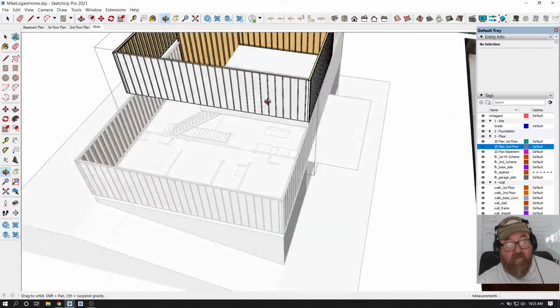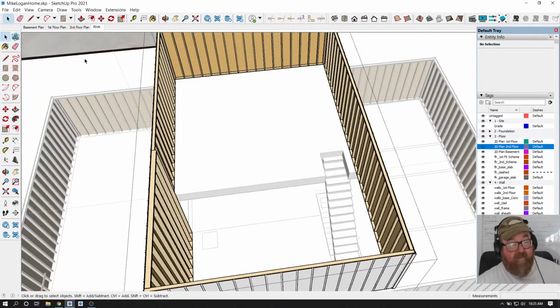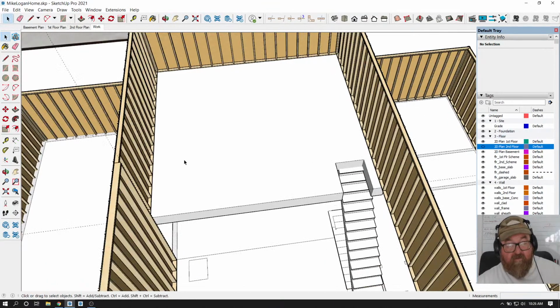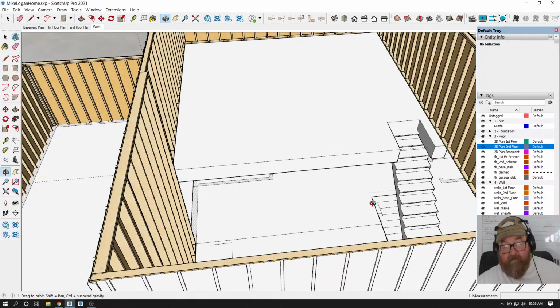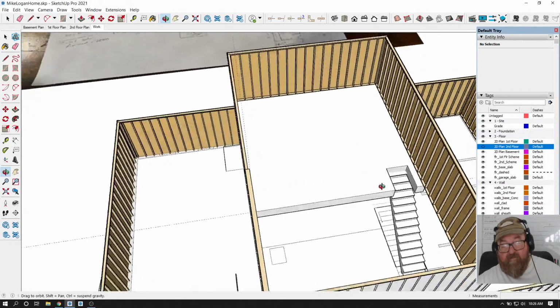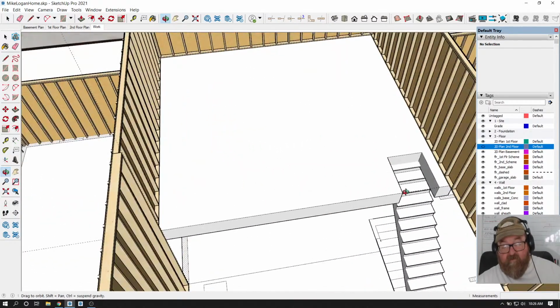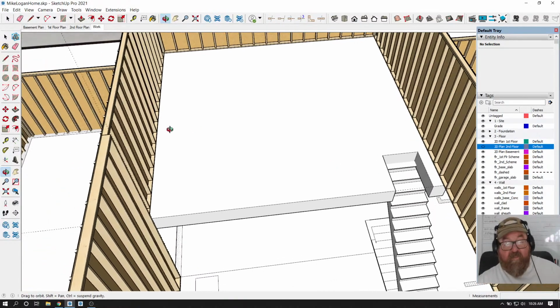Okay, so I don't know what you're talking about, but these are going to be wood eye joists that clear span this whole thing, except right here there'll be a post. Well, there's going to be a wall beside the stair that will support this part of the floor that's hanging over that doesn't have any support. But these main things out here are going to be wood eye joists.